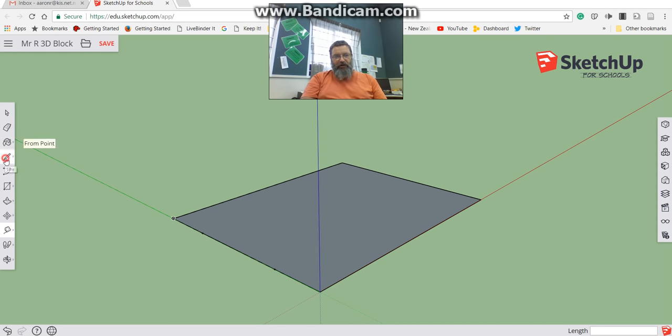I'm then going to go back to my line tool, and from that guide point, and I need it to say guide point before I click, and then I'll click and release. Then I move my mouse until that line turns red, and I'm going to type 20 and press enter. I'm then going to move my line tool over this way, making sure that line turns green, and I'm going to press 20 and enter. And then going to go back.